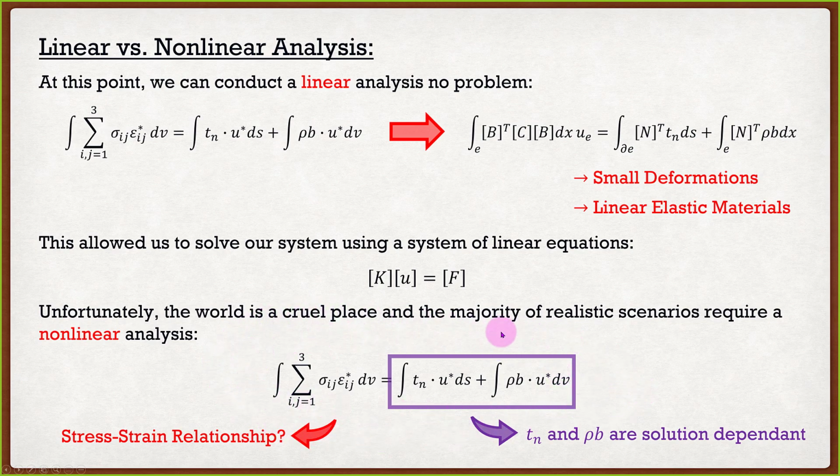Basically, we are going to solve this equation for the unknown virtual displacements such that this equation is maintained. This equation here, you may not remember, but this is basically equilibrium. We're going to iterate through the possible displacements such that our equilibrium is satisfied. Now, we're solving for the nodal displacements, basically every degree of freedom in my system, and that's one equation. And every degree of freedom in the system, that's one unknown in the equation. So if I have 4 degrees of freedom in my system, I have 4 nonlinear equations, and each one of those equations has 4 unknowns. So hopefully that makes sense to you.